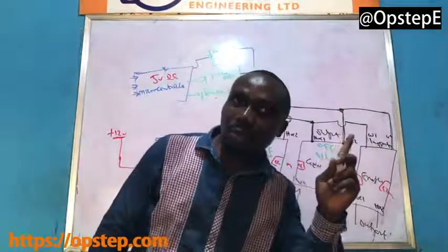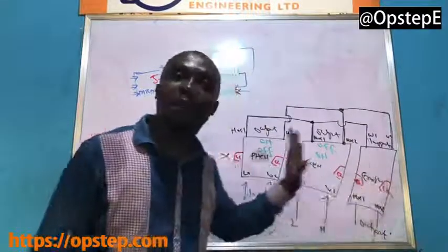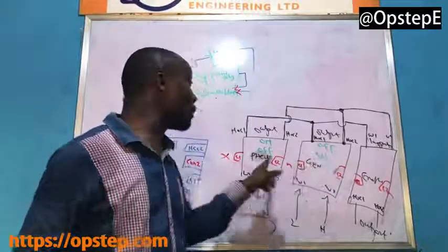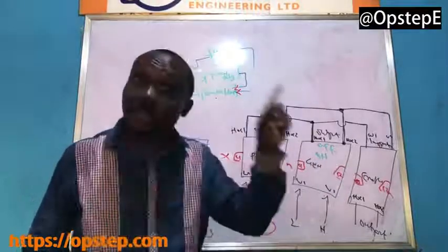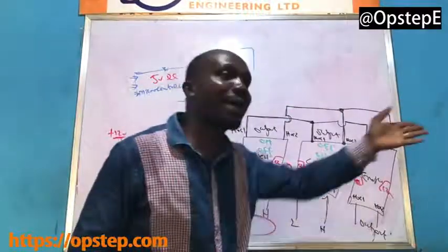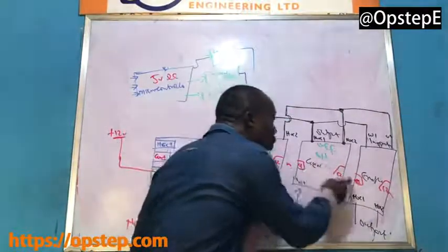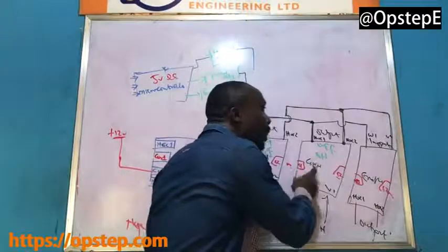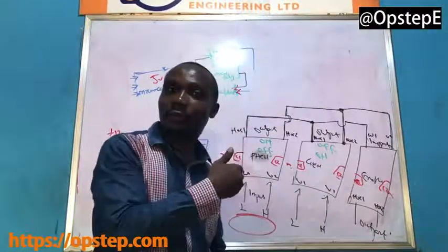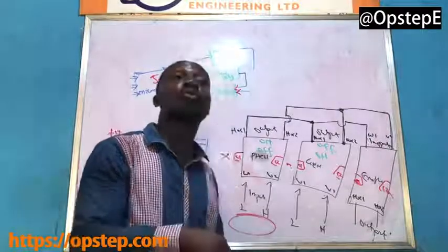No, off the coil. The generator can be running. Which means if you don't even tell it to off the generator and you just switch source to NEPA, the generator will continue to run, but it's not what is supplying, because the coil of the relay that would have switched the generator is off. That's why I said the system is foolproof.